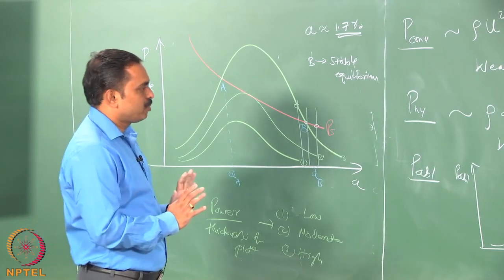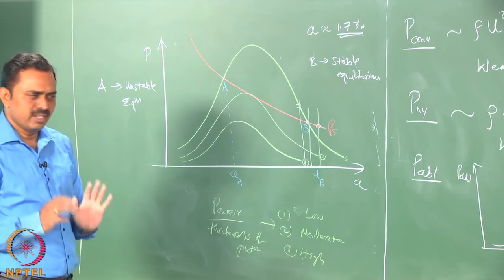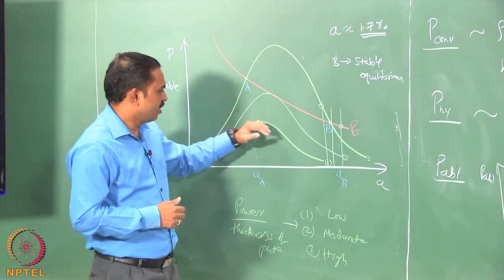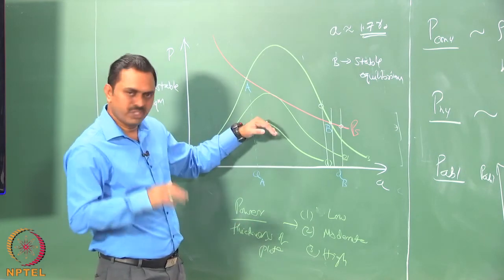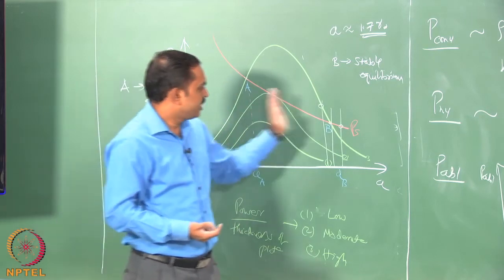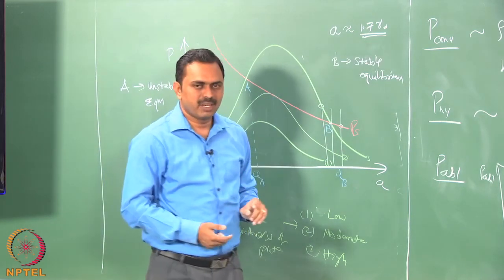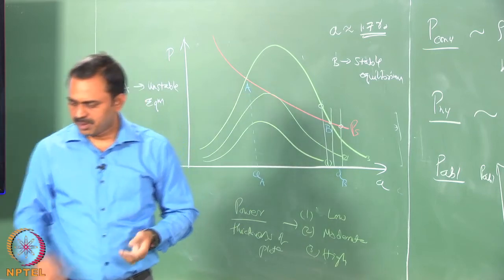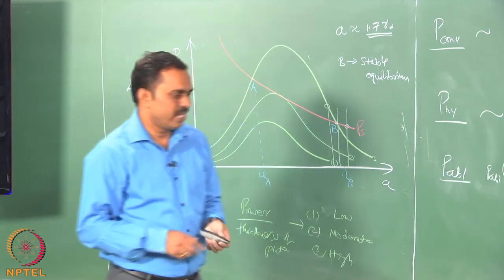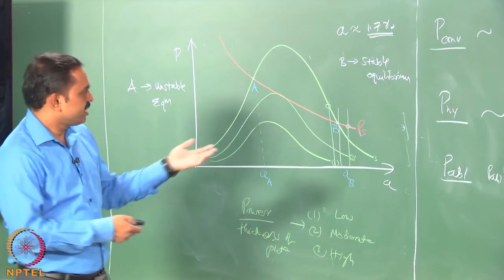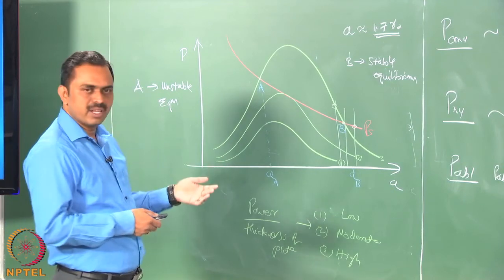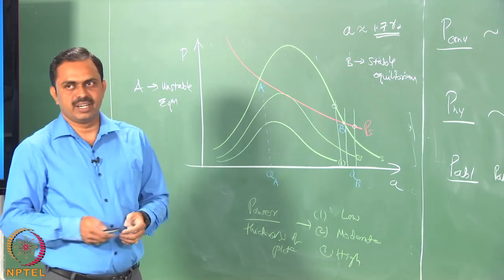But still we are able to come to some conclusions which can be rationalized with respect to the experiments, namely that there are low heat inputs for which you do not have a keyhole, and there are stable regimes and unstable regimes, and the stable regime gives a particular number which also seems reasonable with respect to the observation. So by this kind of analysis we can understand how keyhole mode welding happens, and that it happens in high heat intensity processes such as plasma, electron beam or laser beam welding.